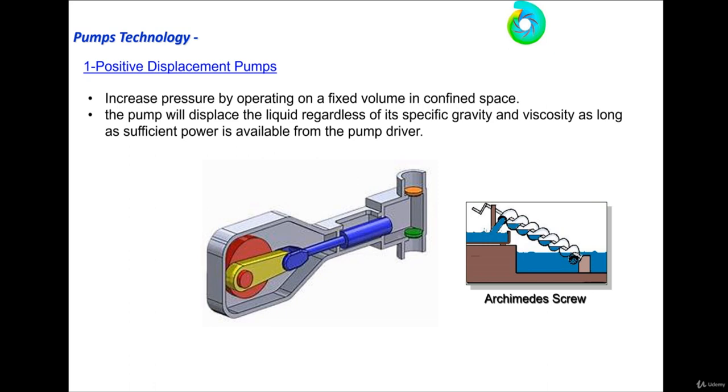You have to be sure that the valves are fully open, because there's a certain amount of flow that has to get out. If you make it partially open, or a little bit closed, this means you are increasing the pressure downstream of the pump, or creating cavitation upstream of the pump.